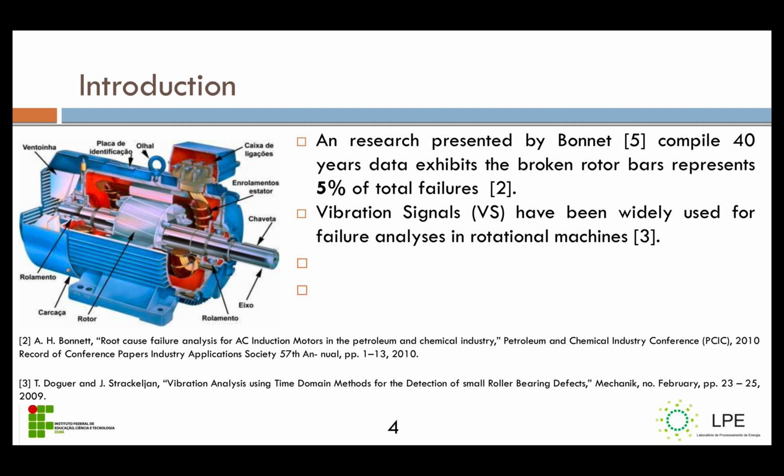And we also encountered papers indicating higher-order statistics, HOS, as a promising technique to describe time domain signals, and researchers have directed their attention to HOS as an auxiliary tool for fault detection on rotational machines. So, our focus is to combine both higher-order statistics and machine learning in order to identify broken bars in squirrel cage induction motors, using vibration signals.